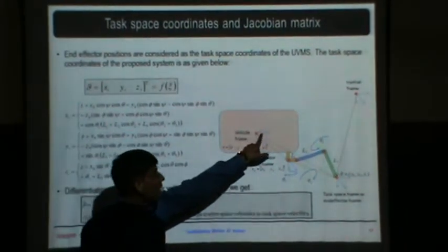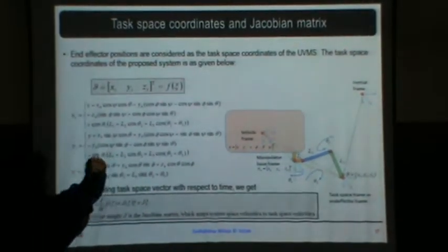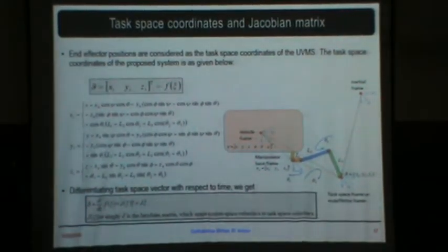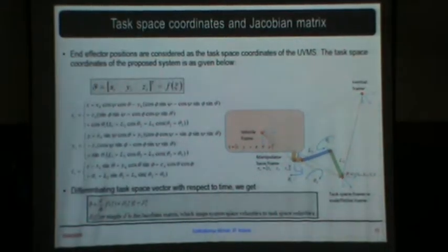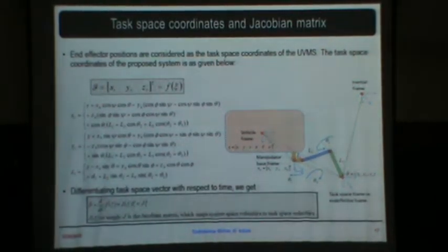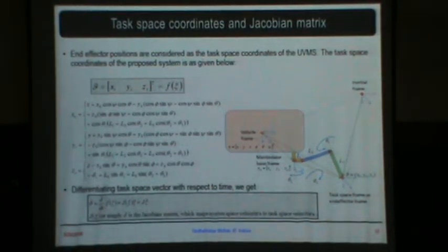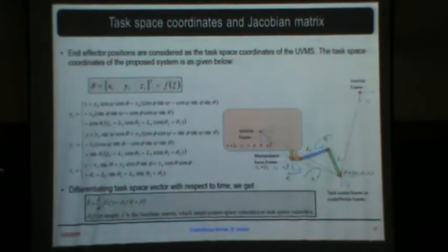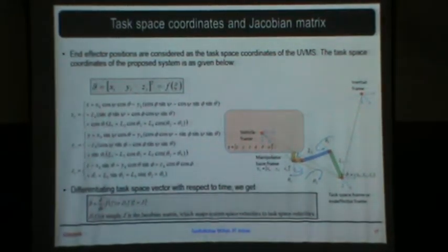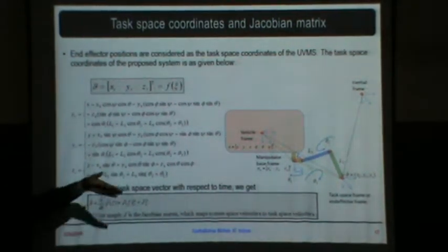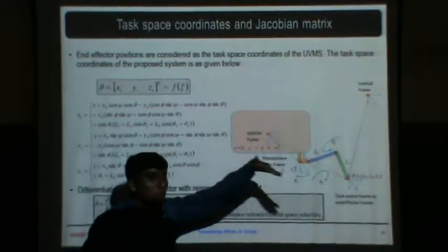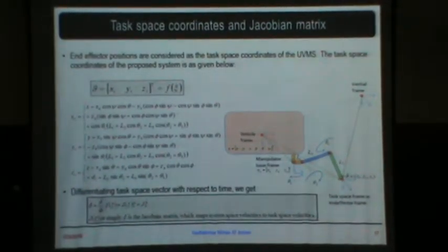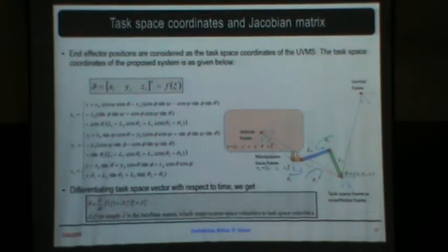So even if your buoyancy shifts a little, the center of buoyancy and center of gravity, even in a neutrally buoyant system, will be slightly shifted. So there will be a pitch. If you end up with a pitch, obviously the system will come down. Just imagine there is a pitch, upward or downward. Usually the end effector is in the front, so obviously the pitch will come in the bottom way only. So it will be like this.